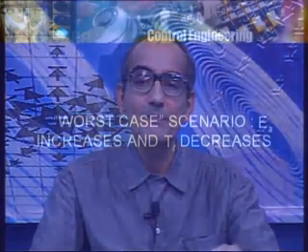But with a larger system, it may be advantageous to use Mason's rule, or it may be advantageous to write down equations and solve them. That depends on what the problem is, how large things are, etc. So we have now a way of figuring out whether the drive is satisfactory. For such and such change in EA only, what is the change in speed and is it acceptable? For such and such change in load torque, what is the change in speed, is it acceptable?